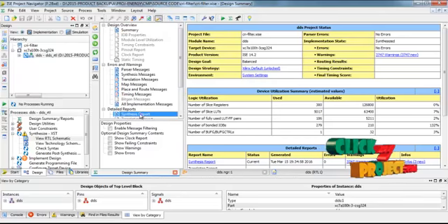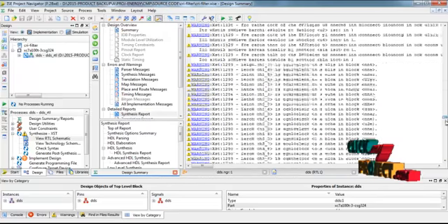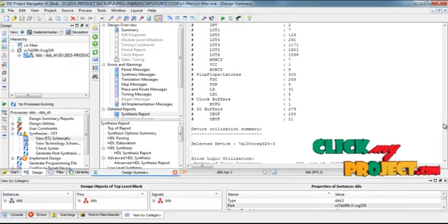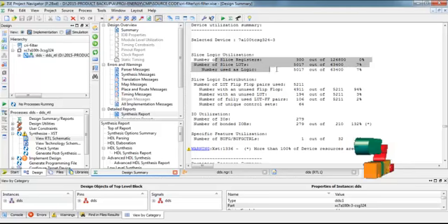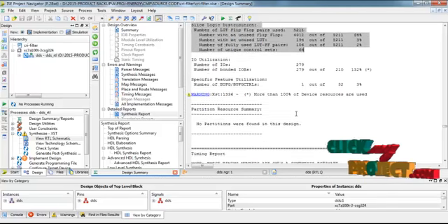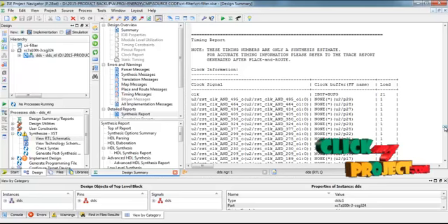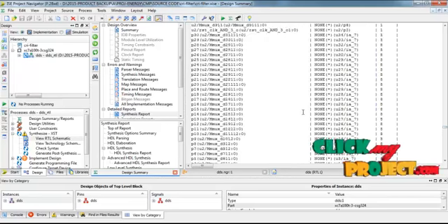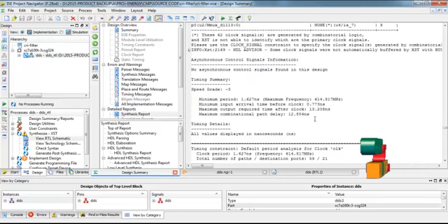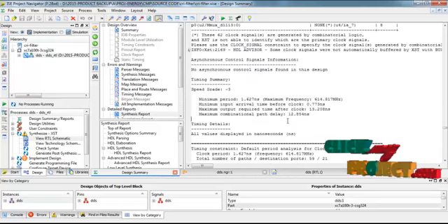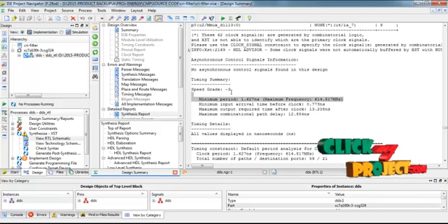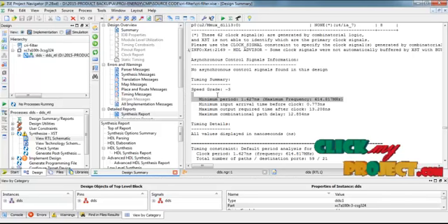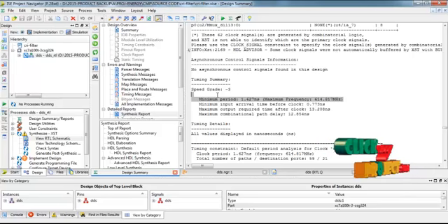Then we go to the synthesis report and design summary analysis for the required device utilization summary, showing how many lookup tables, flip-flops and input output ports are used for the overall architecture. Then we go to the timing summary analysis for the required output architecture. It shows the overall path delay time, the latency time, the clock speed level and the minimum period level for the overall 32 tap FIR filter architecture. This is the final output for our FIR filter architecture.